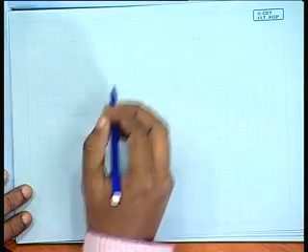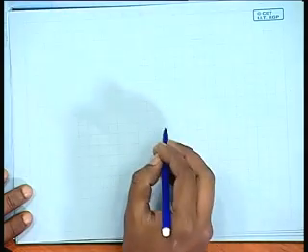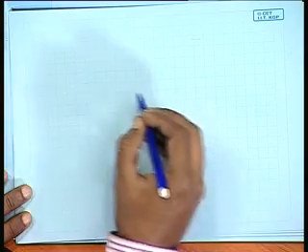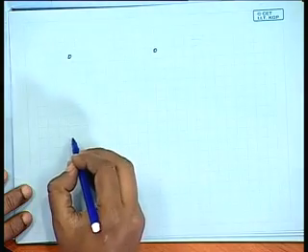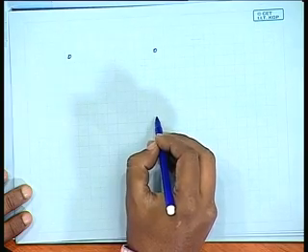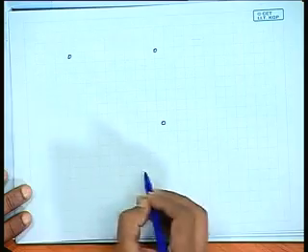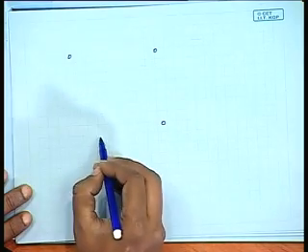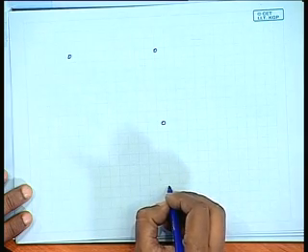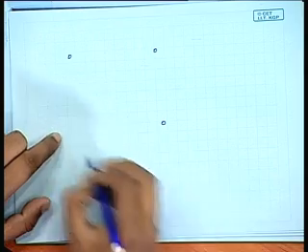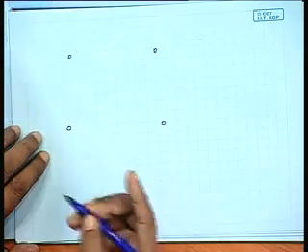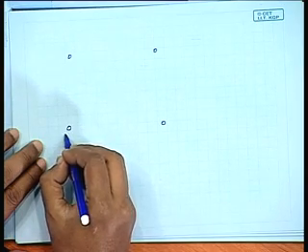This is just as simple as that. But here, we would try to see how this is computed. Suppose in a mine area or any agricultural field or any other places, for our practical purposes, we generally want to find out the hydraulic gradient. The boreholes are like this. Say we have made the boreholes quite regularly. Essentially, it has to be in the form of a grid, always in the form of a grid. So let us compute this one like this. Okay, what we see is the water level here. Say the water head here is 30 meter.